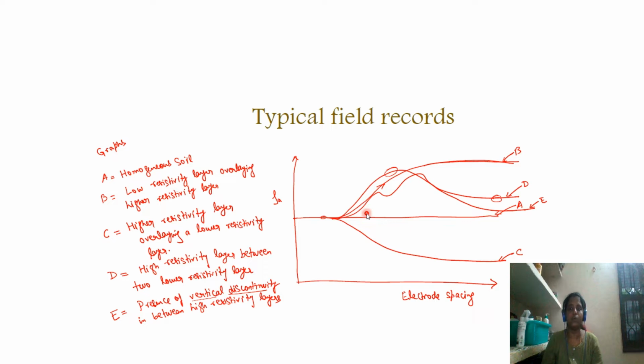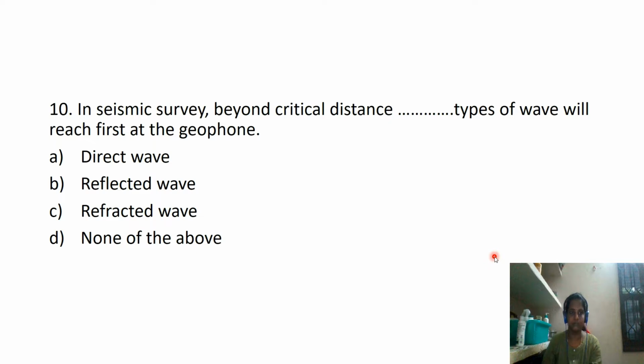So what we are worried about is how the stratum is going to vary along the distance of the highway. For such a project, we use a different array. And when we are worried about larger depth, and I need to find what type of stratum is present, we'll be using another type of array.